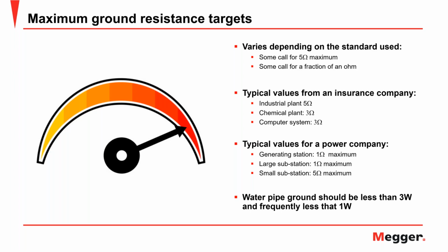The National Electric Code is concerned with safety, with shock and fire. It does not concern itself with good performance, and it says that in the preface or somewhere. So the 25 ohms is a forgiving standard. It is not really a good standard for commercial and industrial. You want to have a much lower ground resistance for those types of applications. Okay, next.